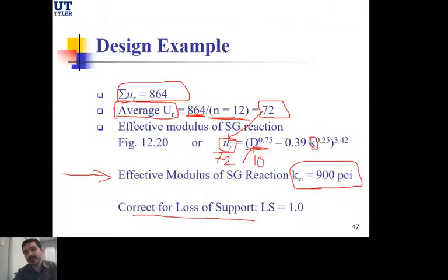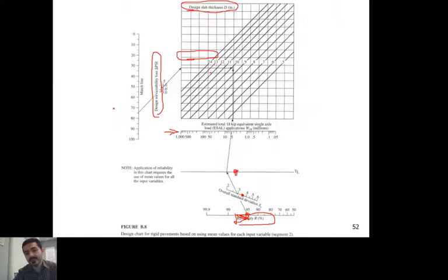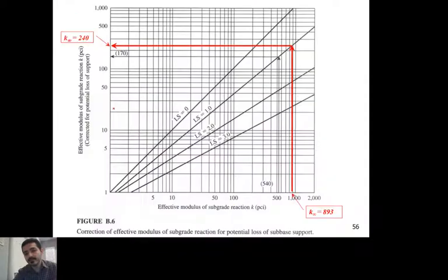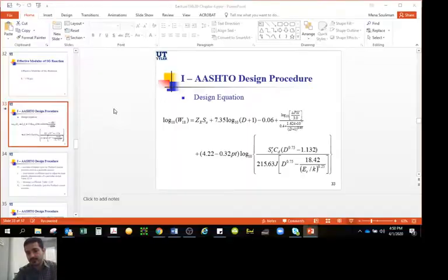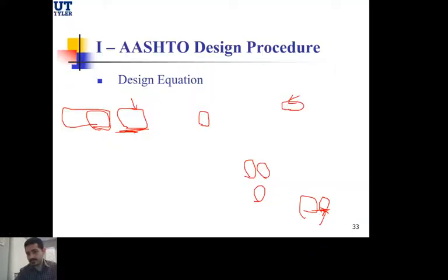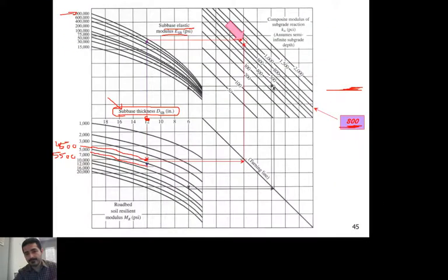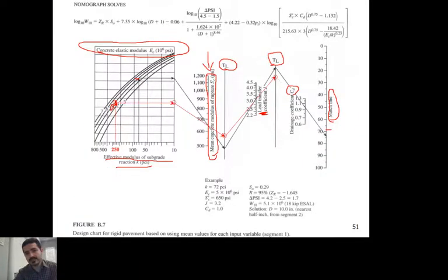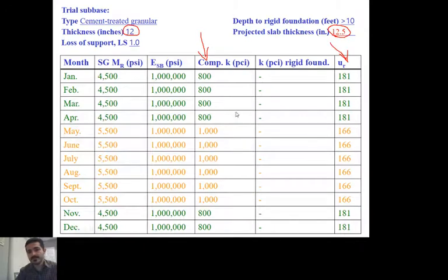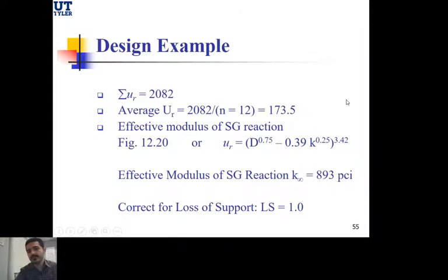What's going to change though is the seasonal variation, the amount of relative damage, because that highly depends on... whoops. Let's come back to here. So we're gonna repeat these steps again. Here, this is not gonna change, but what's changing now is the relative damage. Why is the relative damage now changing? Because the relative damage depends on this equation right here, and this equation doesn't stay as is, because now the D, this is the thickness of the PCC layer. For the first iteration we assumed it's 10, but now it's 12 and a half. That's why we're gonna repeat the